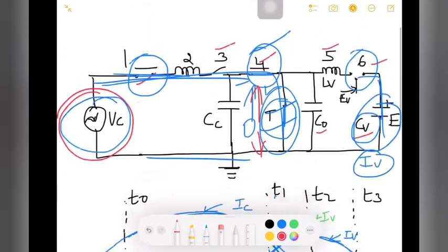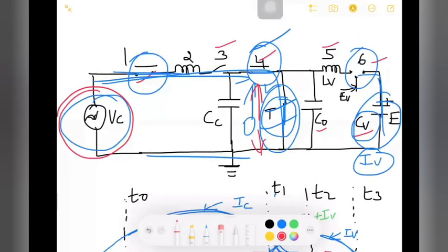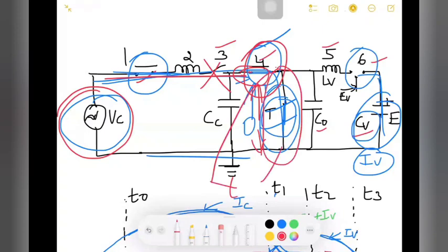That's the reason we use an auxiliary circuit breaker, C4, within the circuit. If you open it, the current flowing here will be disconnected. The test breaker will be connected to another voltage source, which is not shown here. So this is regarding the synthetic testing of a circuit breaker.